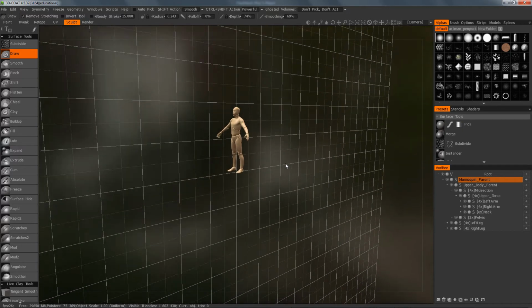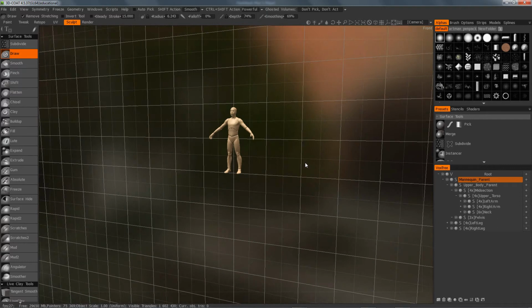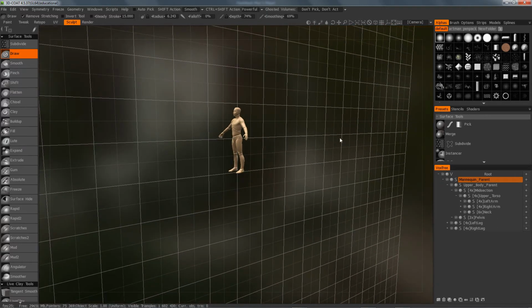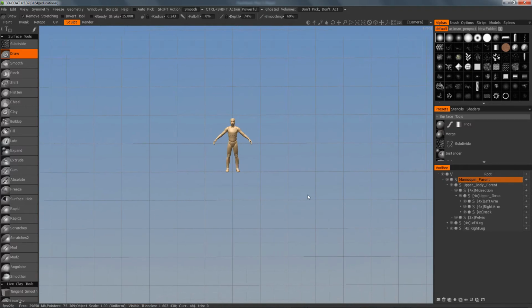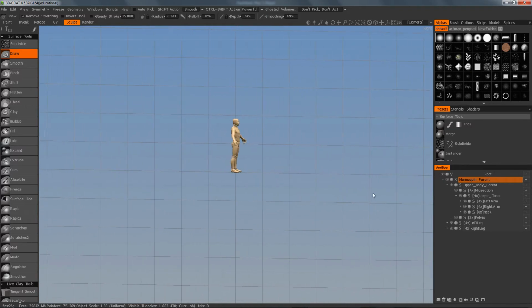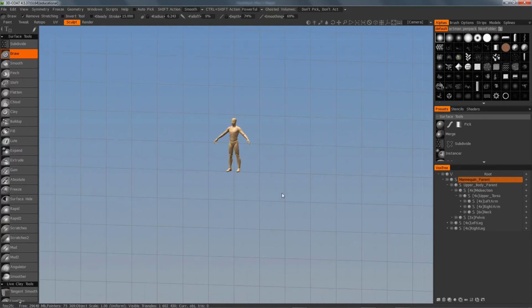Notice how the grid lines retreat to a vanishing point. If I set that to ortho, notice how this also looks like a wide-angle lens. There's perspective on the little box icon. If I click on it, the little box icon becomes parallel. Also, your background environment disappears, and you get a standard gradient. Okay? This is if you want an orthographic sort of treatment of your model.